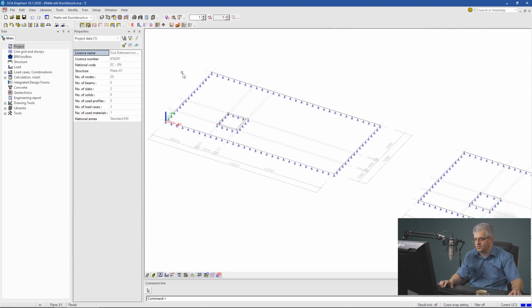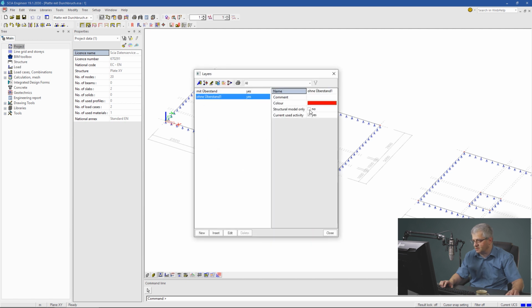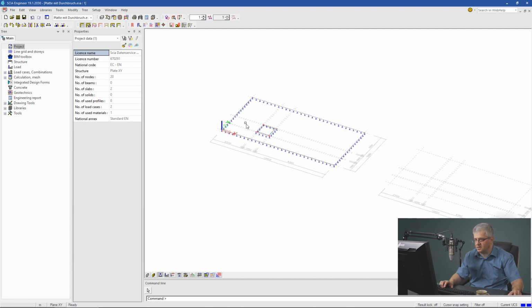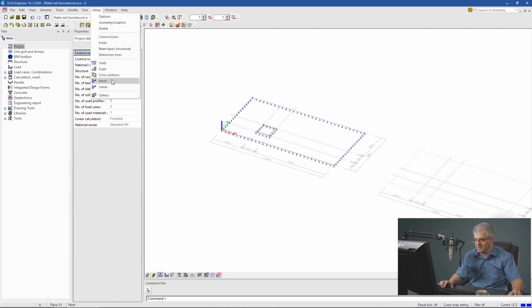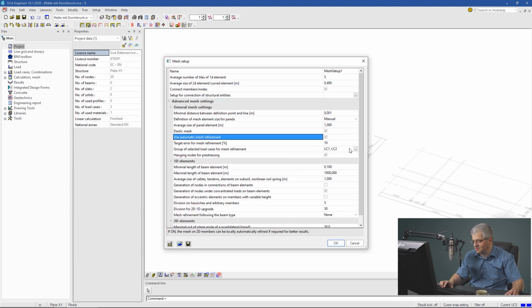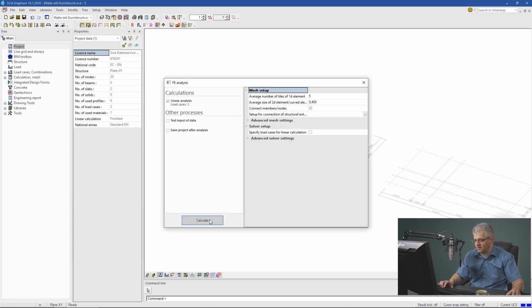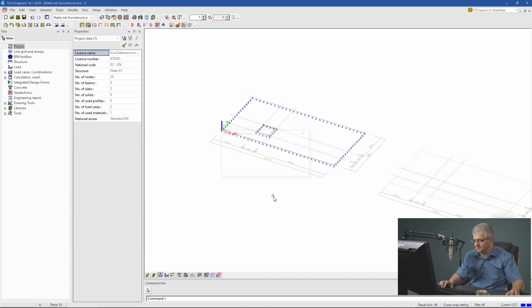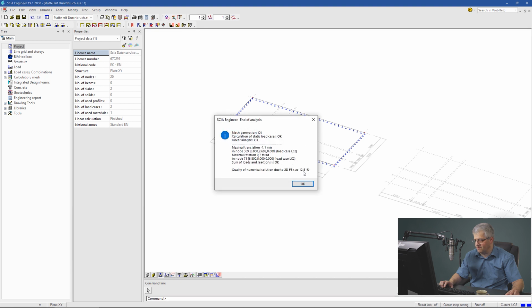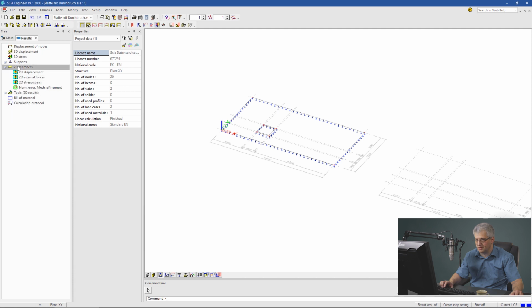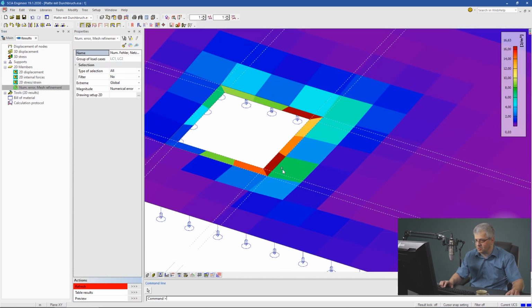And if you look at the precision, I don't know if I have, okay, we will deactivate the right side. We have only the left side. Okay, run the calculation. There is also one hidden calculation. Okay, I have forgotten to activate the mesh refinement. So okay, now it's activated. Calculate the results again. And after that we see 12.5%.